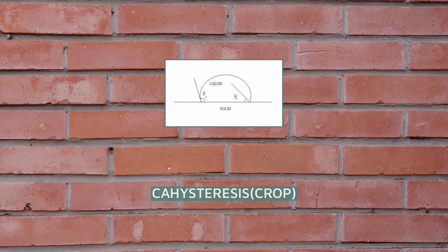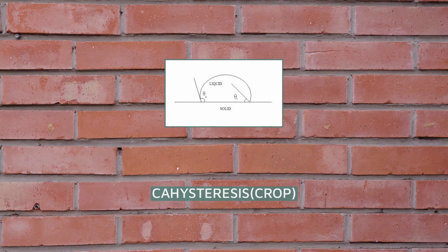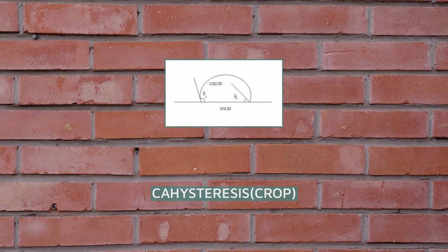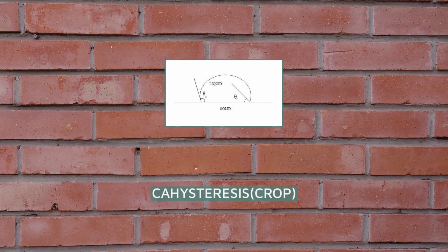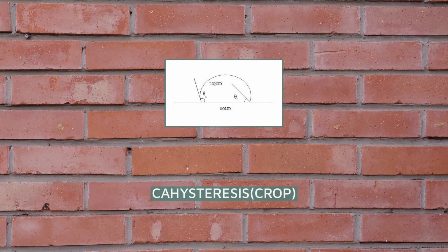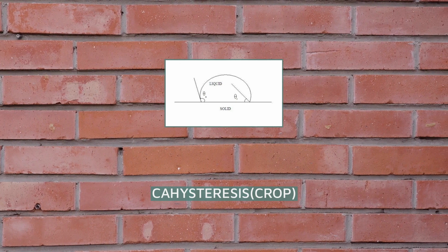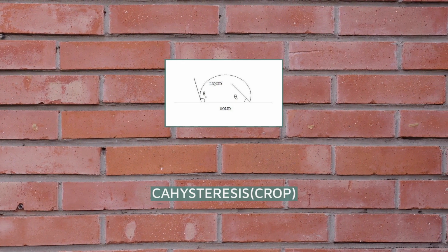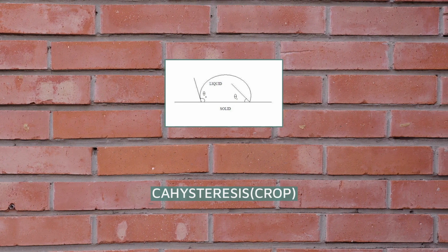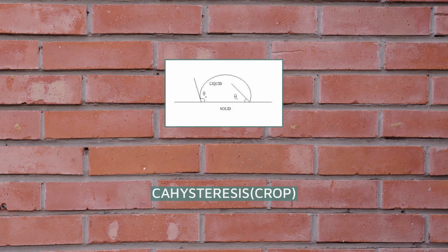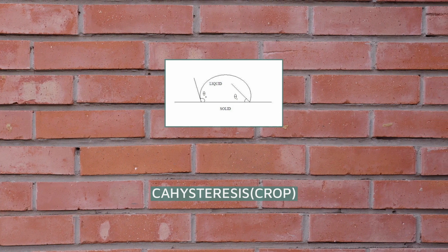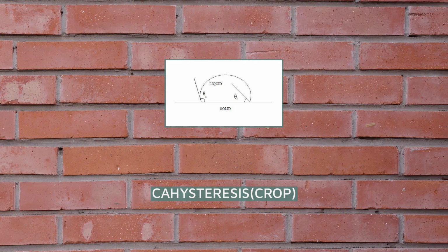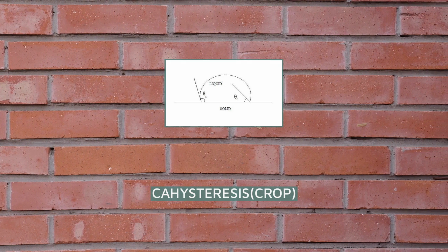When a contact line advances, covering more of the surface with liquid, the contact angle is increased and is generally related to the velocity of the contact line. If the velocity of a contact line is increased upward, the contact angle increases, and as it approaches 180 degrees, the gas phase will become entrained in a thin layer between the liquid and solid. This is a kinetic non-equilibrium effect which results from the contact line moving at such a high speed that complete wetting cannot occur.